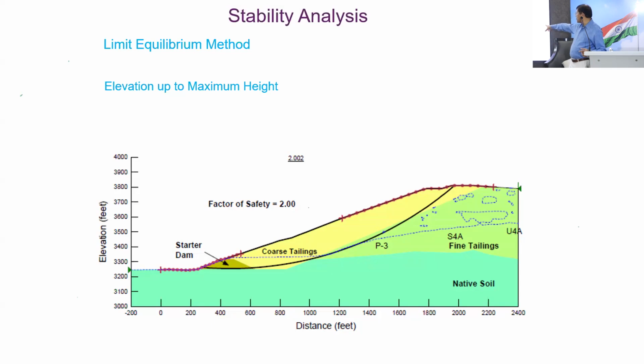You see those points, P3, S4A, U4A, these are some existing piezometers there. But as we go on, we install more and more piezometers at the higher levels. And those piezometers will give us the pore pressure.